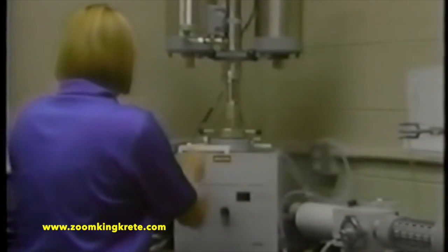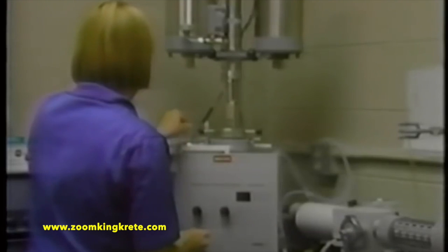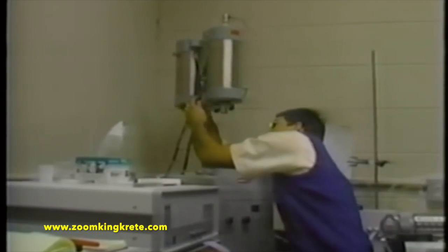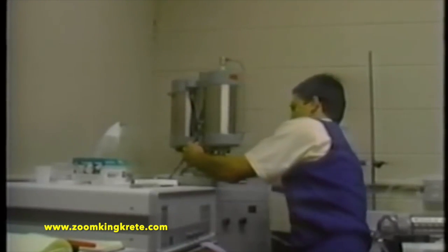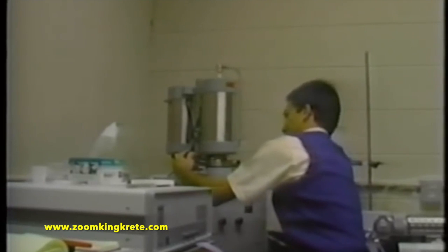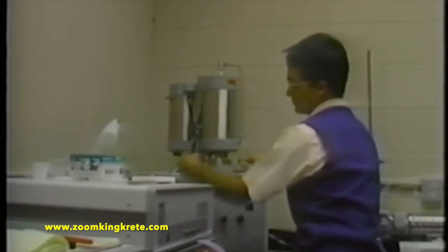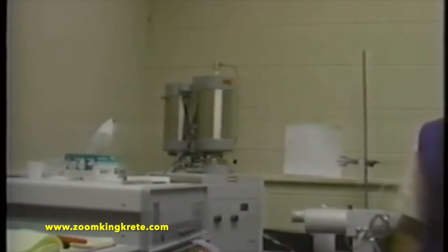Scientists are using measurements of other properties to monitor concrete setting and hardening. Researchers often need to know what portion of the cement has hydrated. The degree of hydration can be estimated by heating a sample of cement paste and measuring weight loss as a function of temperature using thermogravimetric analysis equipment. The free water in a sample is driven out by heating to 105 degrees Celsius. At 105 degrees, the sample is dry, but still retains its strength.